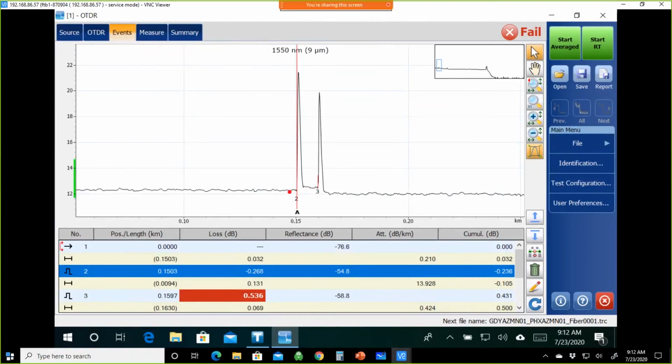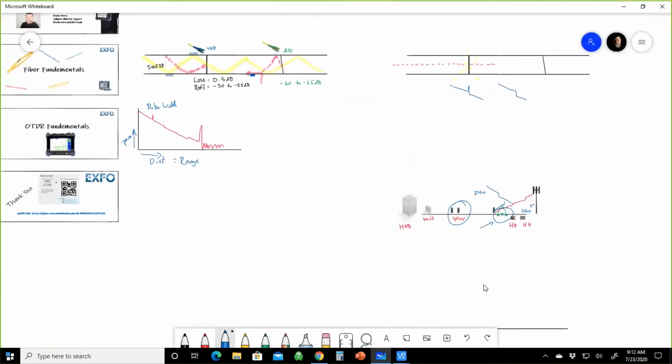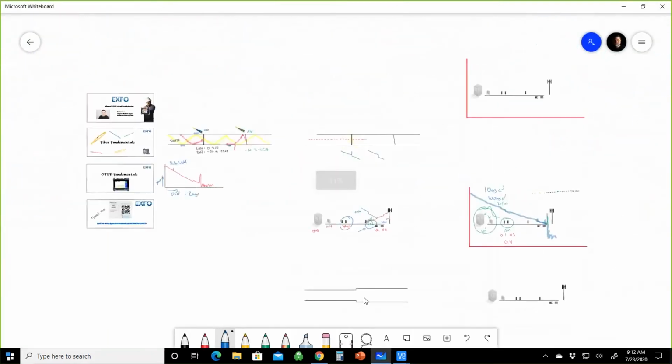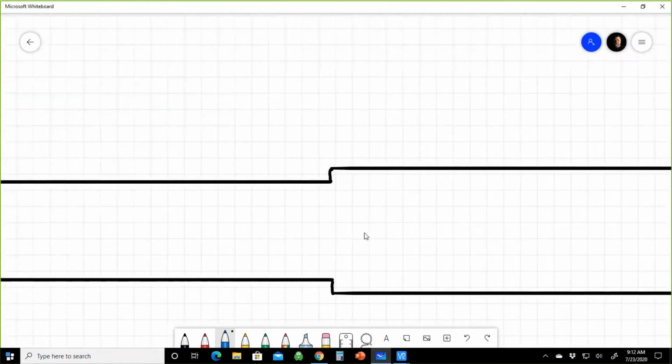Essentially, this right here is regular fiber, G.652D or SMF28, standard single mode fiber. This here is that one 10-meter jumper I told you about. That's a bend-insensitive jumper. And so this is simulating what we call a mode field diameter mismatch. For interpretation purposes, a mode field diameter mismatch is essentially when you splice two dissimilar cores together, and they have slightly different mode field diameters.